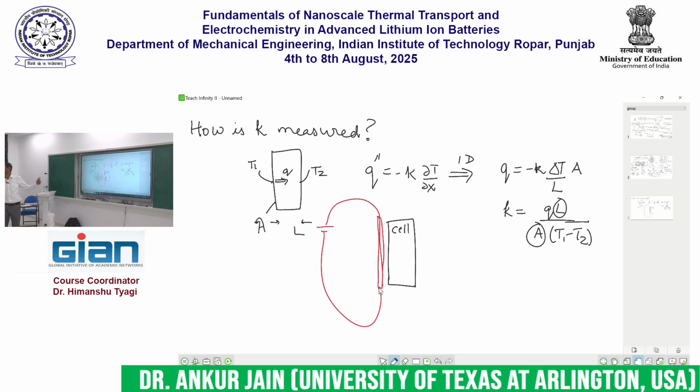Then what is the next step in this experiment? What do we do next? We'll have to measure how much heat we are supplying. How will we measure that? Sure. So I can connect an ammeter and a voltmeter. Yeah, and V times I will give me how much joule heating occurs in this heater, right? Any objections to that? We have to insulate this side also.